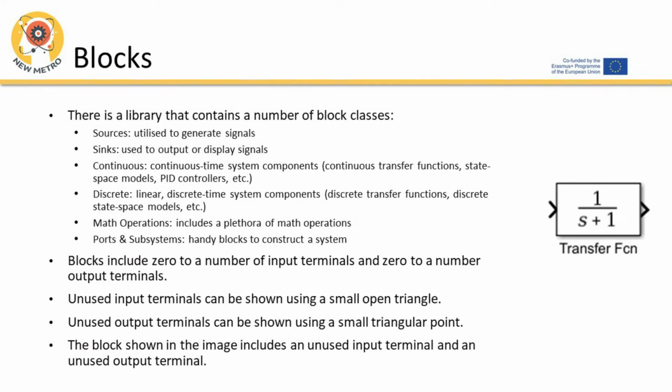Blocks. There is a library that contains a number of block classes. Sources, utilized to generate signals. Sinks, used to output or display signals. Continuous time system components: continuous transfer functions, state space models, PID controllers, etc. Discrete, linear, discrete time system components: discrete transfer functions, discrete state space models, etc. Math operations includes a plethora of math operations. Ports and subsystems, handy blocks to construct a system.